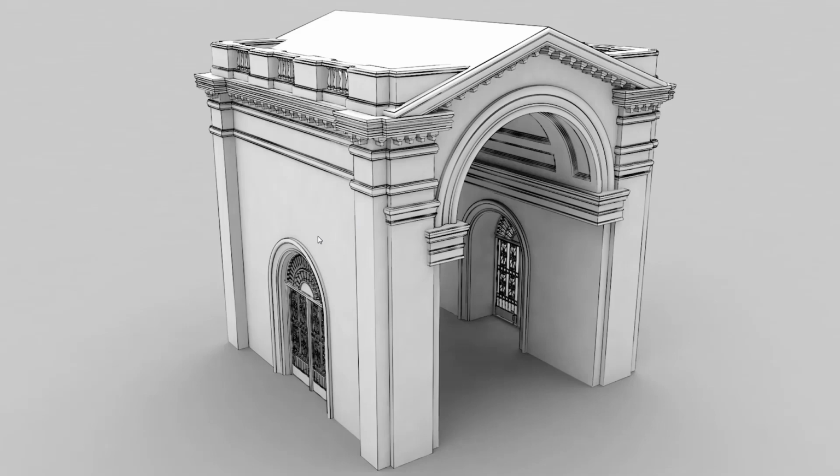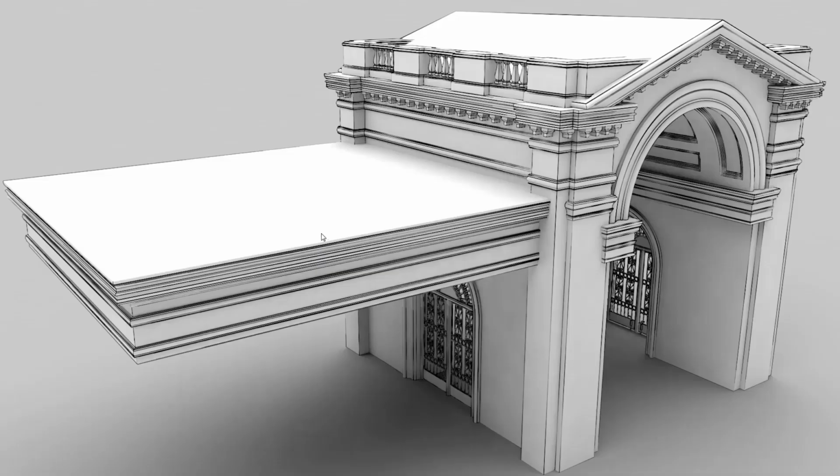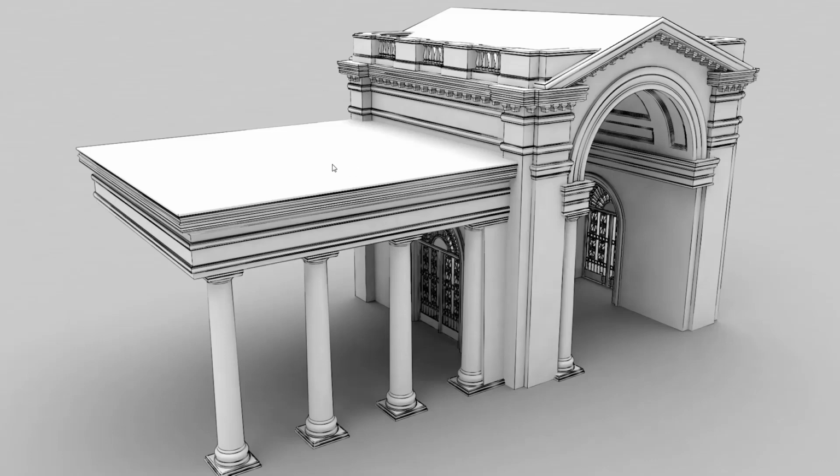Next we will use some splines that we created in part 1 of the tutorial to create the roof, and then we will create some more splines that we can use to create the top and bottom of the pillars as well as the column for the pillars. We will create instances of these pillars and position them where they need to be. We're also going to create an additional square pillar here, and we'll have to make some minor adjustments to some of the objects to make sure that everything fits together nicely.